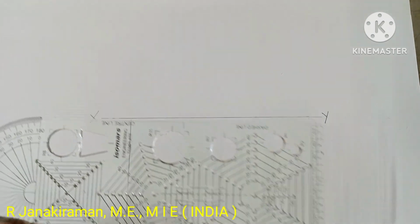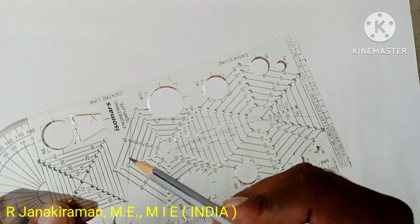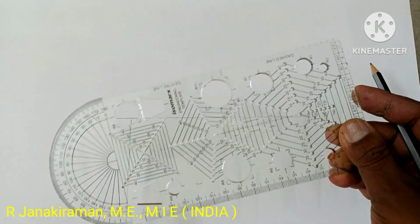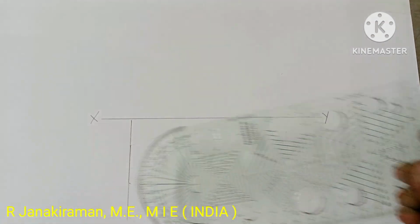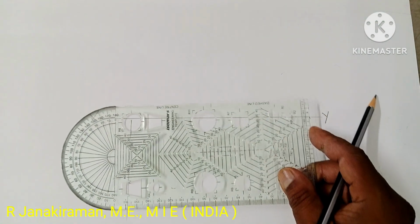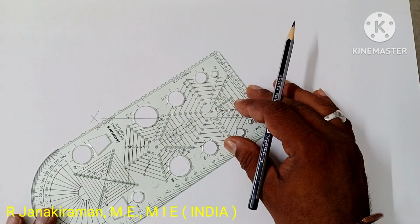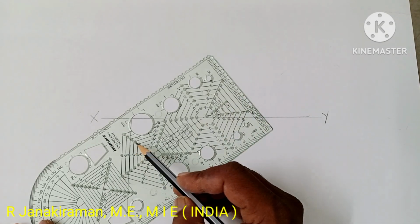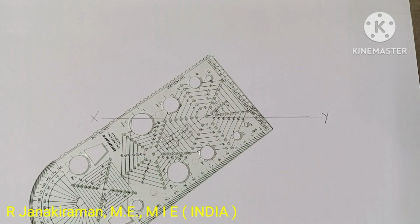For that, any one side of your pentagon, say I choose this 30 mm side. Turn your template so that the 30 mm side and this vertical line coincide. If you keep it like this, it won't coincide. You have to adjust or turn the template. So the 30 mm side of your pentagon must coincide with the vertical line drawn below the XY line on one side.